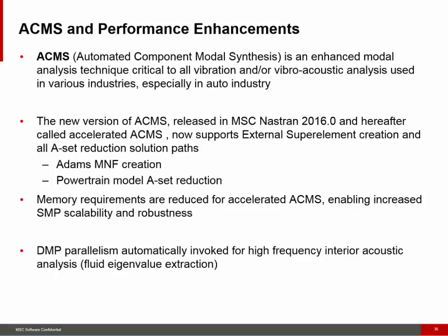So the new version of ACMS we released in MSC Nastran 2016 is now called the Accelerated ACMS method. It now supports generation of external superelements. And that can be, for example, an Adams MNF creation, or you have a powertrain which you want to reduce down to its A sets, which may be, for example, the main bearings and the cylinder liners.